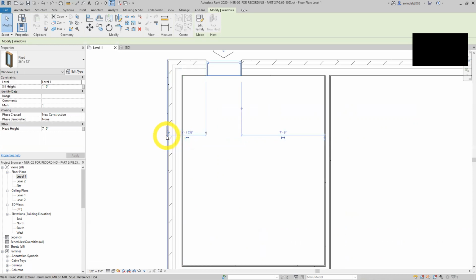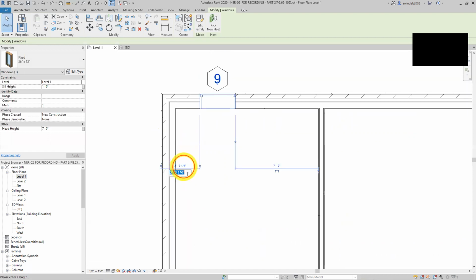This is something also to help you annotate better. So say you want to go to a specific spot to annotate from. This is very powerful. 4 feet from that spot, or, if you hit that icon, it works as well. So we'll say now inside wall. That's my datum I want to go from.